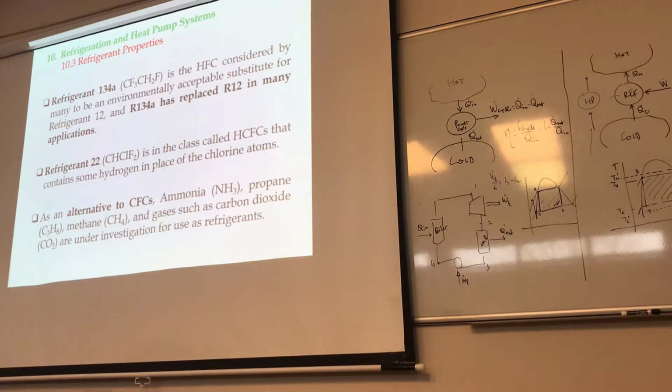Usually you are trying to cool a space that is below what the conditions are in the atmosphere, right? So what you want is to have those at atmospheric pressure. If you look at the properties of the refrigerant at 1 atmosphere, they're just going to be a gas, so that they could do their job at least at the evaporator level.